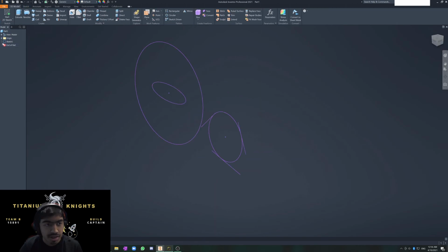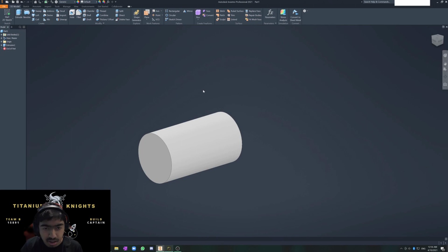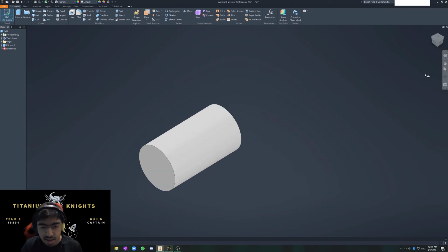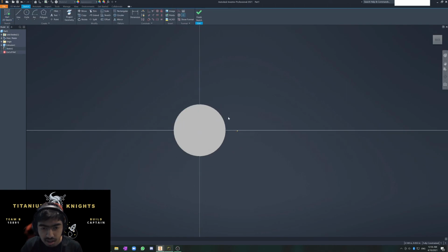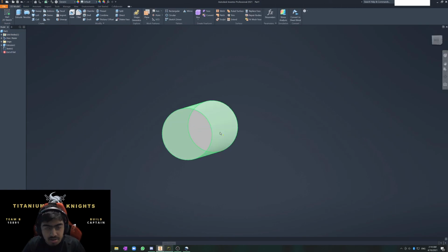You can also create sketches on 3D faces. So you'll learn to do this in a later video, but you can extrude a closed object into a solid object, and then you can hit start 2D sketch or press S and start a sketch on any flat surface here or there. So I can just do this, and then you get a sketch here in which you can define objects. So I hope this video was helpful.